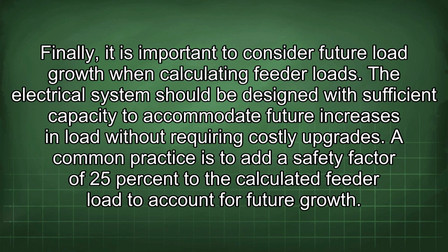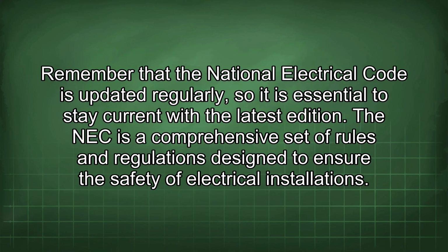Finally, it is important to consider future load growth when calculating feeder loads. The electrical system should be designed with sufficient capacity to accommodate future increases in load without requiring costly upgrades. A common practice is to add a safety factor of 25% to a calculated feeder load to account for future growth. Remember that the National Electrical Code is updated regularly, so it is essential to stay current with the latest